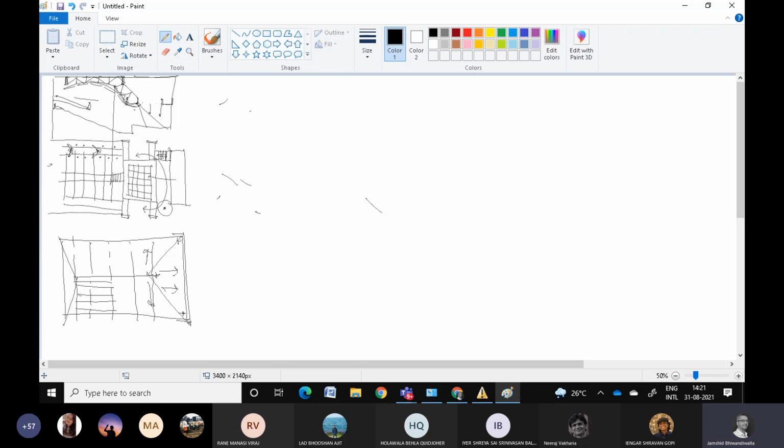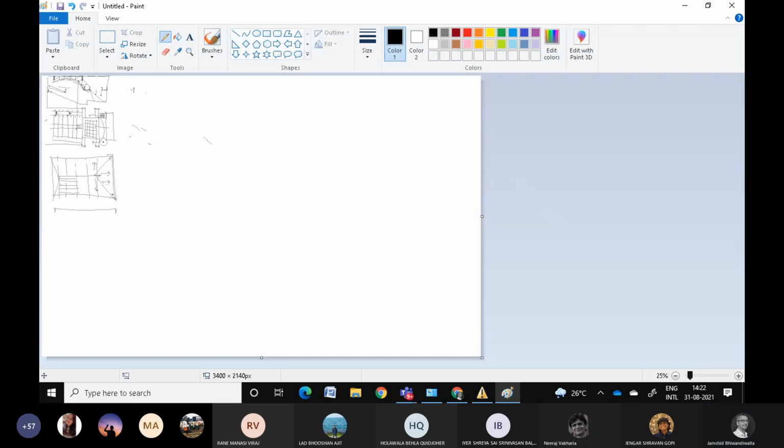What I'm trying to say is that if I have a slab that is as large as this, then the water tends to collect in the center and that would lead to leakages. In such cases, it makes sense if you break up the roof. So part of the roof is higher, part of the roof is lower, so that this water drains off easily to these areas and then drains off further below. So big flat roofs over auditoriums rarely help.